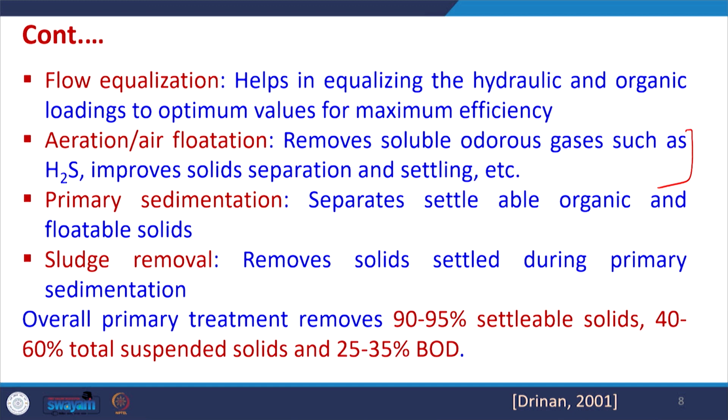After the primary sedimentation, where coagulation and flocculation steps are performed, the sludge is ultimately settled and taken off for treatment, and the water obtained after the primary treatment is further taken for secondary treatment, which is generally biological in nature.